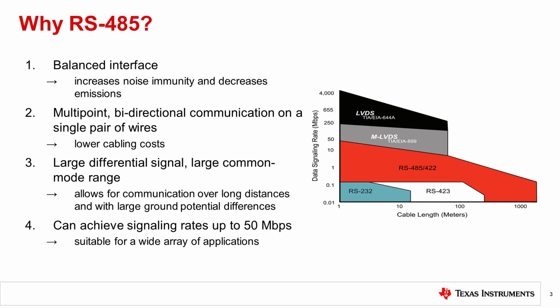An RS-485 driver is required to drive a large differential signal into an RS-485 load. This enables the signal to travel across long distances while still being large enough to be accurately interpreted by the receiver. An RS-485 driver and receiver are also required to operate over a common mode range of -7 volts to 12 volts. This enables data fidelity in the presence of large ground potential shifts relative to other interface standards, and may also extend the operable distance of an RS-485 transmission line.